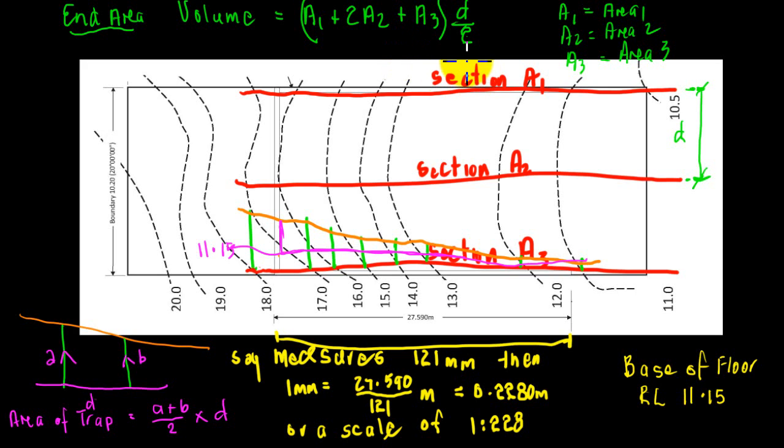So first thing we've got to do is draw the section, but before we do that, as is quite common in the business that we're in, we quite often get plans that have dimensions and scales on them, but those plans have been printed out from a PDF or run through the photocopier or various things. So for various reasons the scale we're working with is not true. So the first thing we've got to do in this job is work out what the scale of the plan that we're working with is.